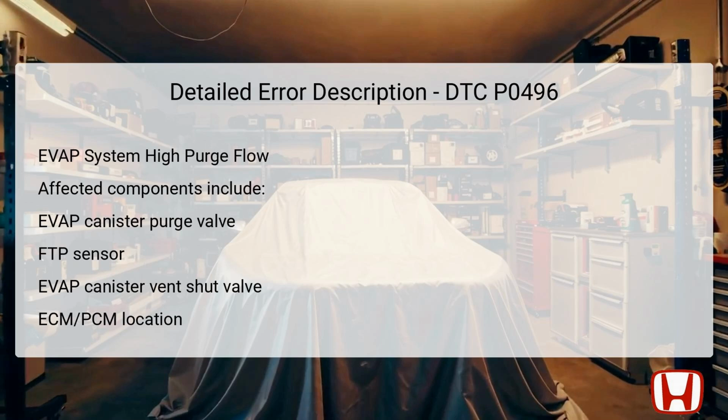The Engine Control Module, ECM, or Powertrain Control Module, PCM, interprets signals from these sensors and valves to regulate the EVAP system's operation. Identifying any faulty components will be crucial in resolving the high purge flow error.